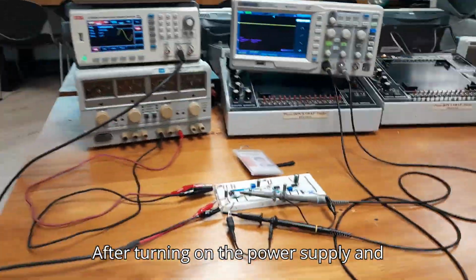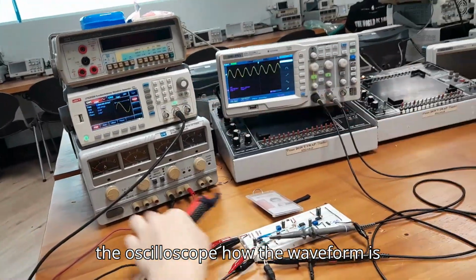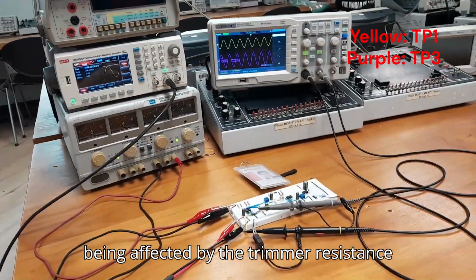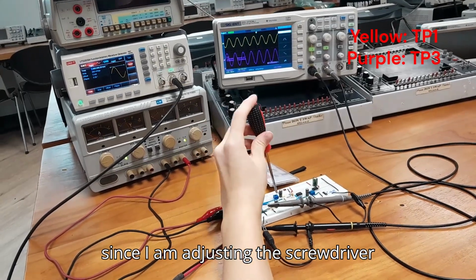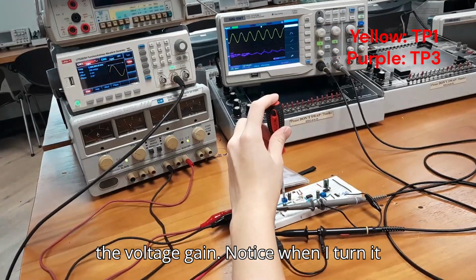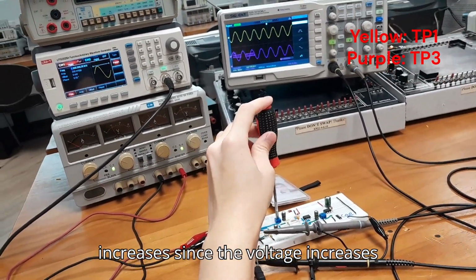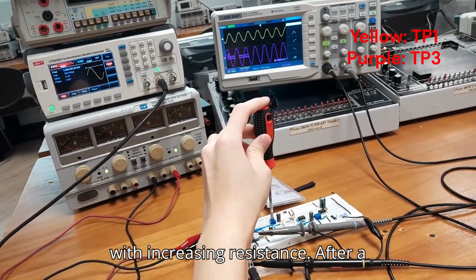After turning on the power supply and function generator, you can then see on the oscilloscope how the waveform is being affected by the trimmer resistance, since I am adjusting the screwdriver which adjusts the resistance and affects the voltage gain. Notice when I turn it clockwise, the amplitude of the graph increases, since the voltage increases with increasing resistance.